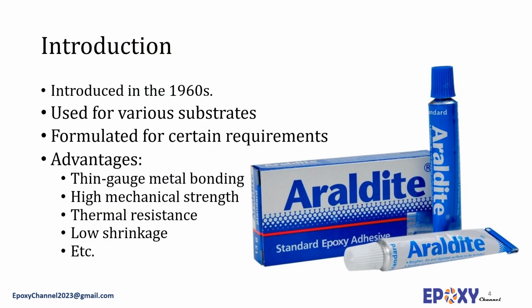Adhesive is defined as a material which, when applied on substrate surfaces, can join them and resist their separation. Epoxy adhesives were introduced in the early 1960s. They are capable of bonding different substrate materials, for example, metallic alloys, aluminum, wood, concrete, glass, ceramic, and various other substrates. An improved fatigue performance of the bond can result from using these systems by providing relatively uniform stress distribution